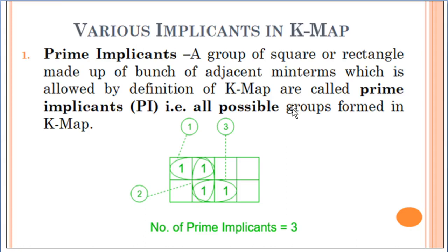That means in a particular given binary function or Boolean function, each term of that function, and each min term or max term of that function, is known as its implicant. Clear? And a prime implicant of the logical function is a term that cannot be combined with another term to eliminate a variable.